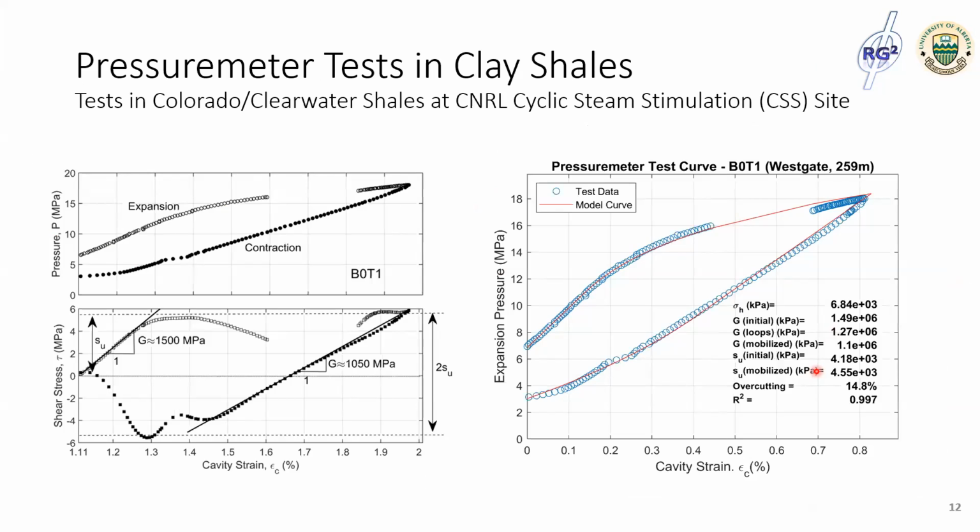so the ideal condition is that the borehole has the same size as the Pressuremeter, and then it will match the analytical solution pretty well. But in reality, we have a borehole bigger than the tool. That's why we have to consider the effects of this initial condition in our interpretation.